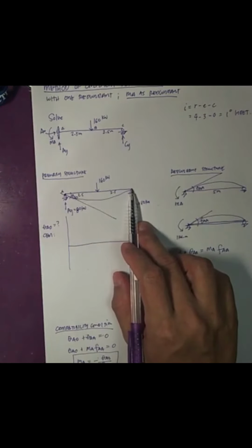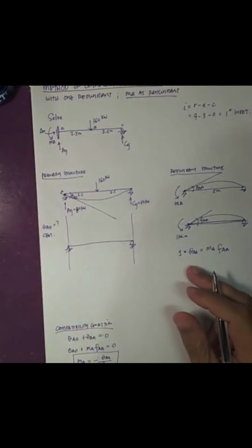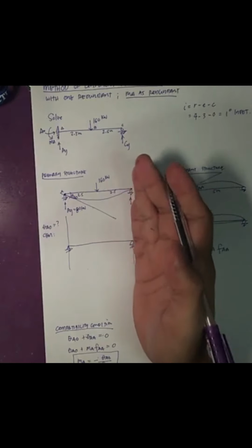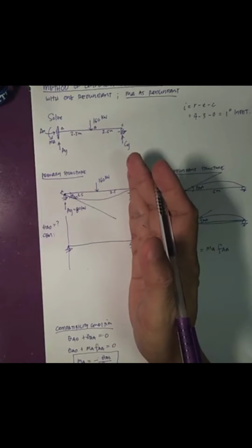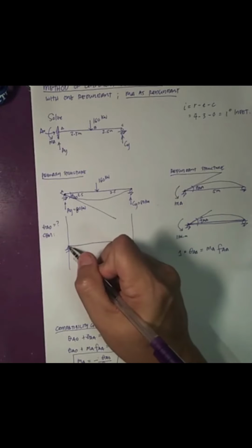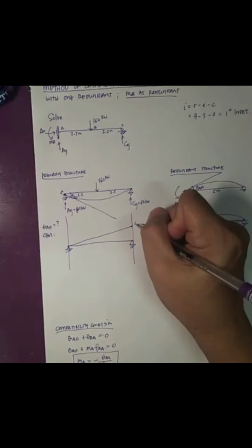So for this original beam, simple beam, the conjugate beam would be almost the same. So hinge roller supports. Then I'm going to draw the moment diagram by parts. Okay, so if I take this as my reference, what would be my moment diagram by parts? Due to the 80 kilonewton AY, I will have a triangular moment diagram here. So 80 times 5 is 400.